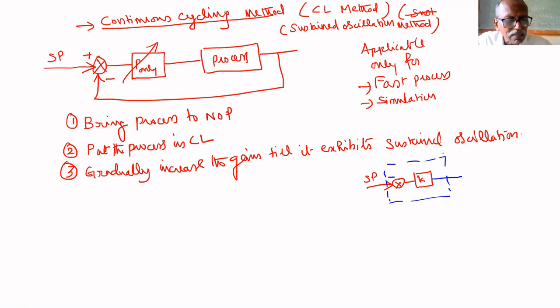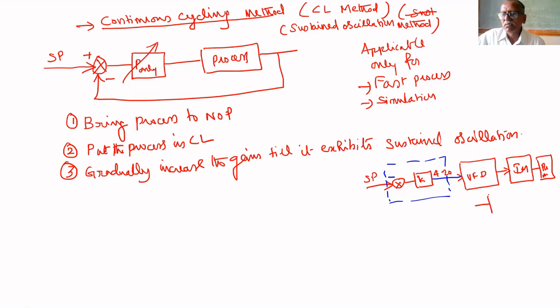The output of the controller, 4-20 milliamps, is given as input to the VFD. The output of the VFD drives the induction motor. The induction motor in turn drives the pump.